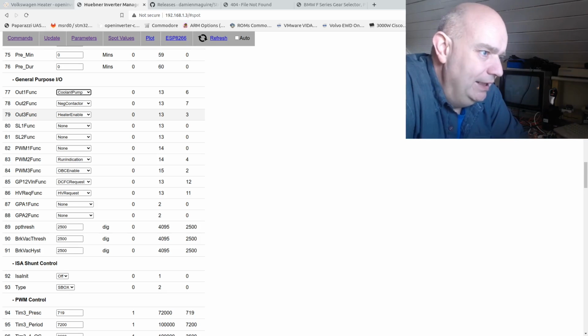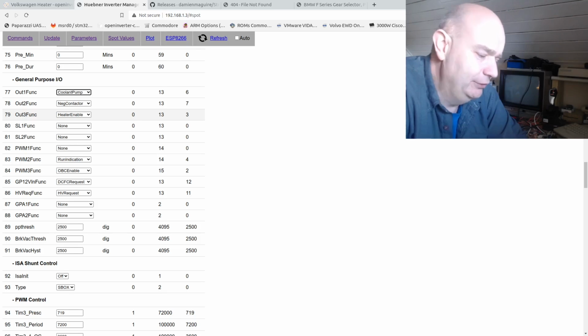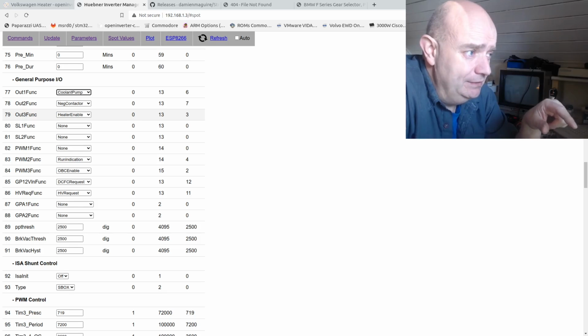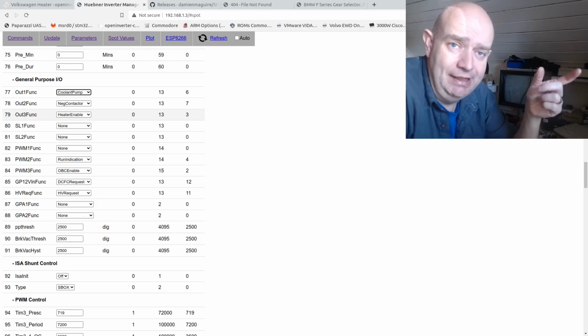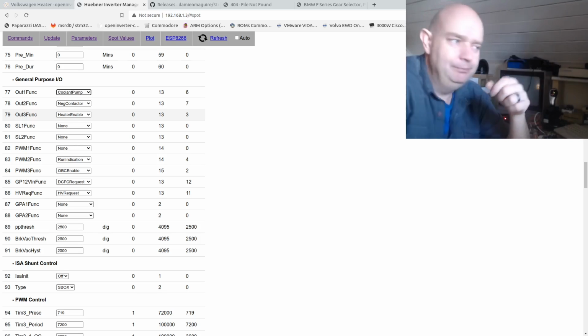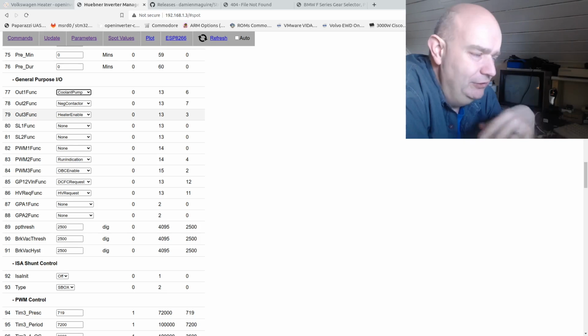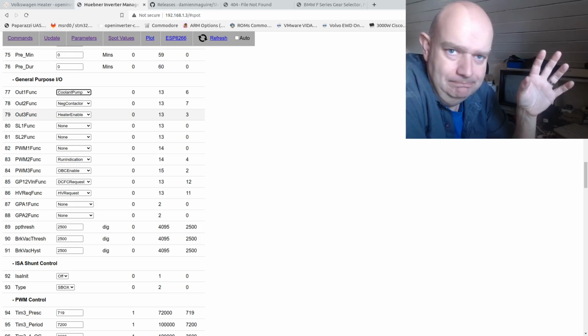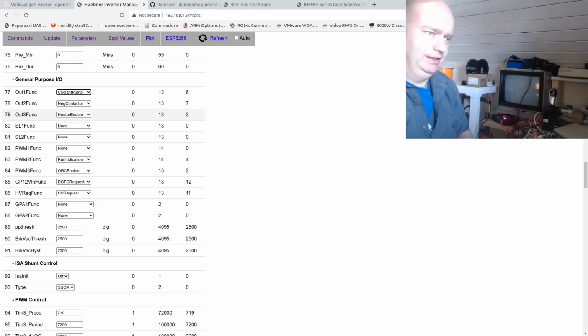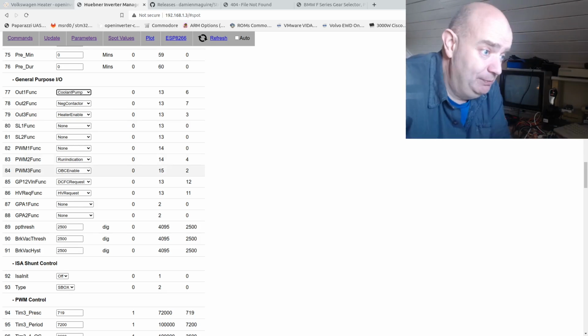So be aware that I would say certainly no more than 500 milliamps. Let's say I use them, for example, in the Panzer, for controlling the alternator warning light on the dash. That's just a little pygmy lamp, right? And there's no problem with that. You can use them for providing a 12 volt enable signal, say, into a charger or something like that. So just be aware of that.